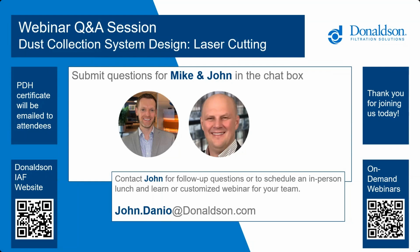Another follow-up question about capture velocity. Is the capture velocity of 150 feet per minute measured across the face of the hood? I feel like we kind of addressed this, but let's just make sure that their question was answered. Yeah, the point where the fume, dust, and particulate is being exhausted to the ductwork of the collector should be at a minimum 150 feet per minute. Hopefully that answers the question.